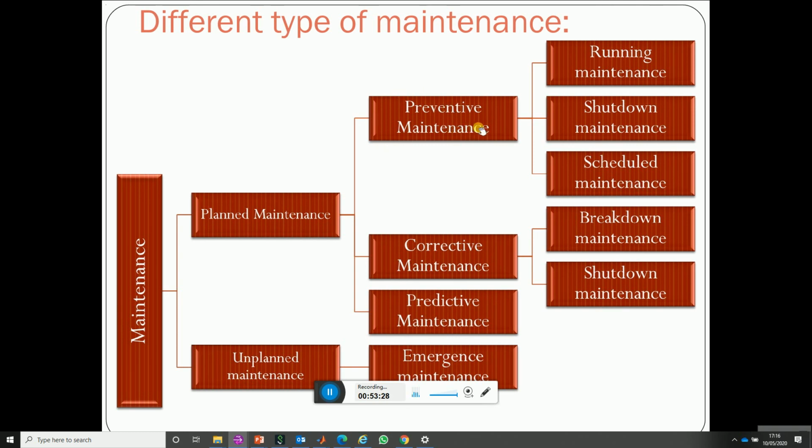Preventive maintenance can also be, for example, on heat exchangers of air conditioning systems. So we wash the heat exchangers now and then to not have any blockage. People do it on their cars every few months. You take your car and you wash the radiator, because it gives you better performance, because it eliminates all the blockage that has occurred in the radiator. So preventive maintenance is things that we do on a regular basis to address a specific fault mode, to ensure we have better efficiencies and maintain functionality at its best.